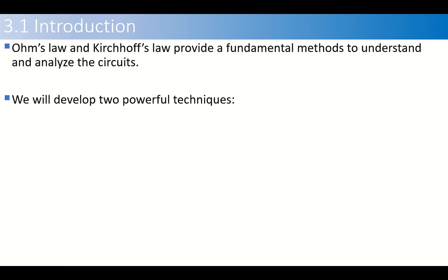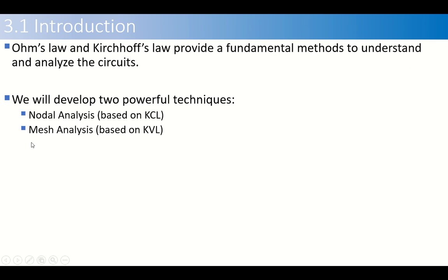So we will develop two more powerful techniques here, that is nodal analysis based on Kirchhoff's current law, and then mesh analysis that is based on Kirchhoff's voltage law. These two important methods that we'll be discussing in this chapter are based on Kirchhoff's laws.